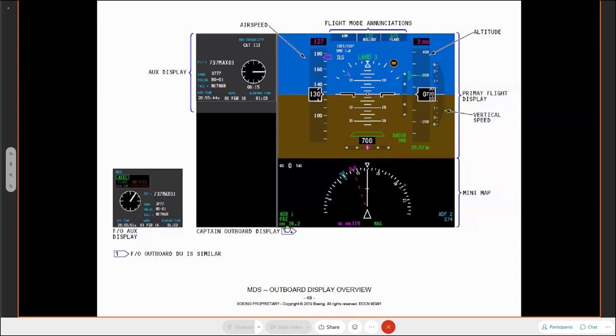Down here, you've got information relating to VOR and ADF. No real information at all to do with the ADF. VOR number 1 or number 2, whichever you've got selected. This is the ident. This is Pane Field, PAE. When you initially tune a VOR, normally they're tuned automatically by the flight management computer, but you can manually tune the VORs. It will show you the frequency you've tuned, and then it will show the ident.